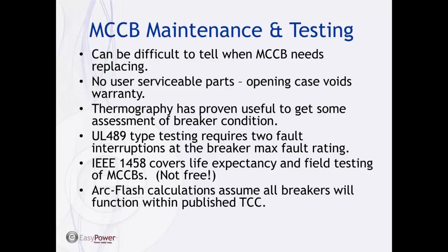There's an IEEE 1458 standard that's not free, unfortunately, but does cover life expectancy and field testing of MCCBs, and it does talk a bit about thermography, so that might be something you want to get if you're interested in that. In terms of how long the breaker is supposed to last and what it's supposed to be able to do, there's no real clear-cut answer to that.